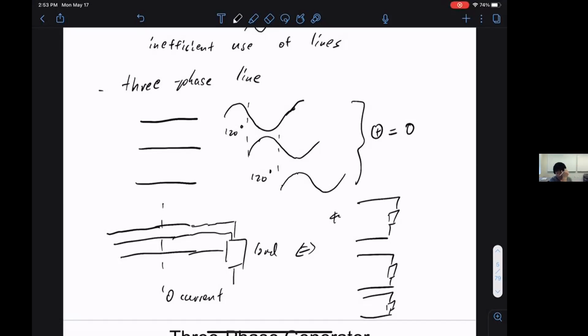Okay, so I'll do the last check question. So it's correct that normally we have a fourth neutral wire. So for safety, you may have a fourth neutral wire running this way, right? Just in case they're not exactly balanced, right? So sometimes you have a fourth neutral wire, sometimes you don't. But again, the fourth neutral wire does not have to have the same capacity as the three lines. You can get away with a much smaller wire.